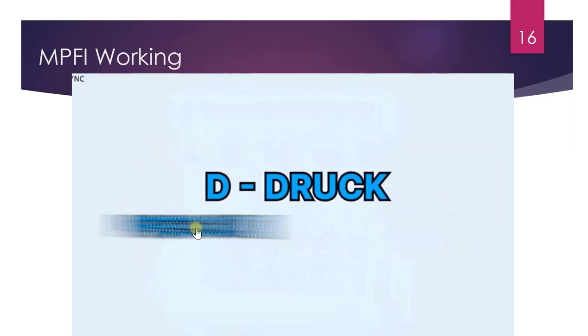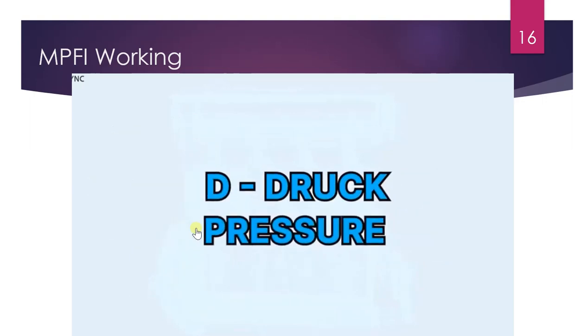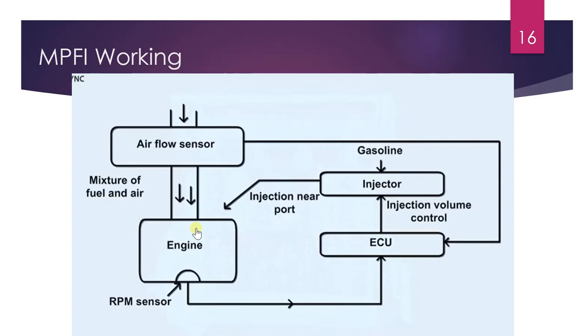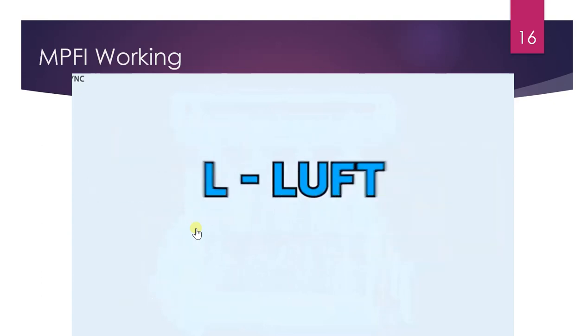D stands for Druck, which refers to pressure in German. If the main input signals to the ECU are the airflow rate and the engine speed, then that system is said to be an LMPFI system. L stands for Luft, which refers to air in German.